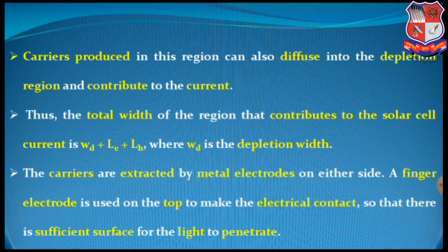So this was all about the principle, that is the photovoltaic effect, its construction of the PN junction diode, how the p-type and n-type semiconductors are arranged inside the solar cell construction, and the working, in which the main aspect is the recombination of electrons and holes, which majorly contributes to generating electric current inside the PN junction diode.